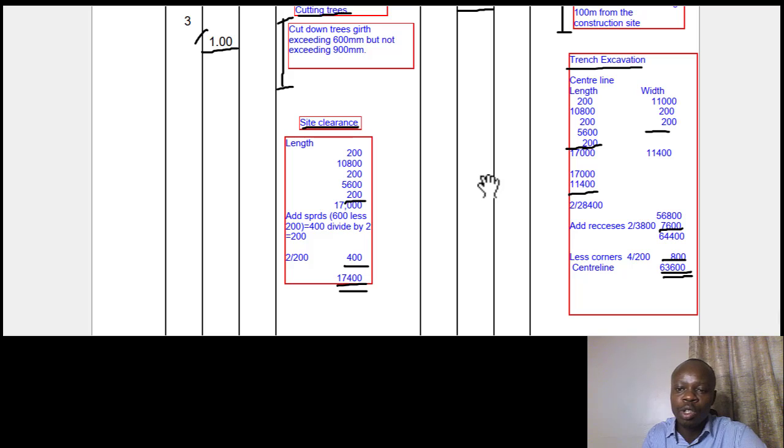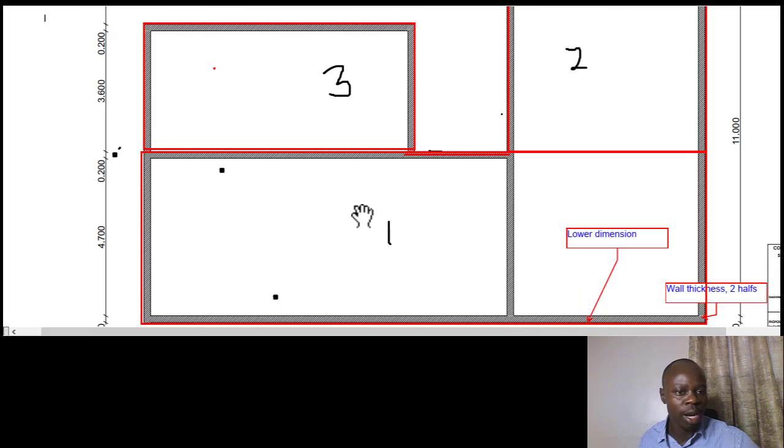The same dimensions, if we get them from the reference of the center line, and then we do adjustment to get the one to the internal point, it will be like a +1 -1, because we are making our reference point at the center line. We are going to add the same dimension to get to the internal point, because the wall is sitting at the center and the trench footing or the foundation footing has equal internal and external spread.